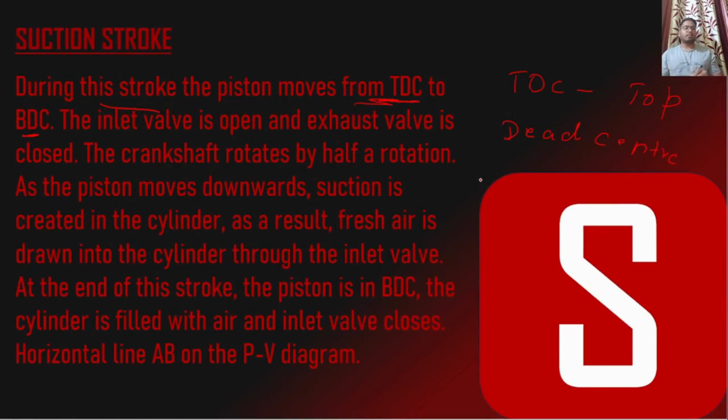The inlet valve is open and the exhaust valve is closed. The crankshaft rotates by half a rotation and the piston moves downwards.